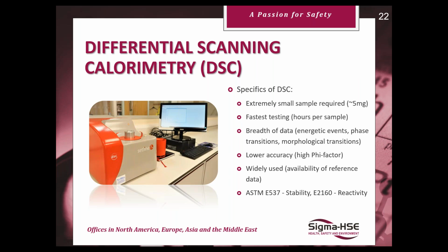It will heat the sample to 400 degrees, typically at a rate of 5 degrees a minute. So the test all in all only takes a couple of hours. It's quick, very useful if it's a reaction that's very early on in its development and you don't have much sample. It's the perfect sort of screening test to get an idea of any energetic events, phase transitions, morphological transitions. So yeah, it's quite a handy bit of kit.